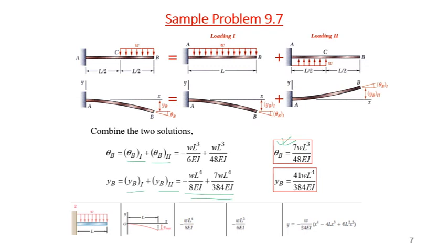Now, you can find these values using the equation of the elastic curve as well, using this differential equation first. With that you can find an equation of the elastic curve and you can solve it. But you can also solve using those values for known curves by doing the method of superposition.